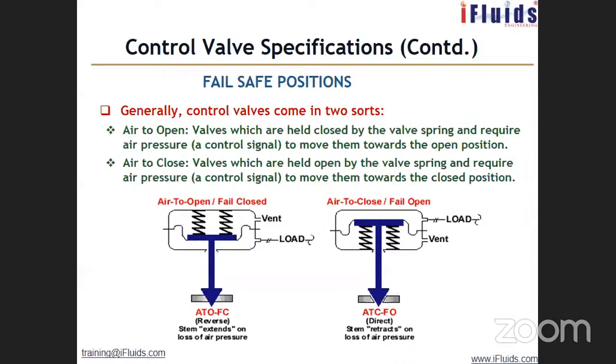Flashing is nothing but when you allow the liquid at boiling point, a slight difference in pressure may reach the vapor pressure of the liquid. So the pressure drop across the valve is sufficient to reach the liquid vapor pressure, then the liquid starts vaporizing in the valve itself. That is called flashing. And that flashing causes the cavitation. So it may damage the valve internals also. And when the valve is designed for liquid service, it cannot handle two-phase.